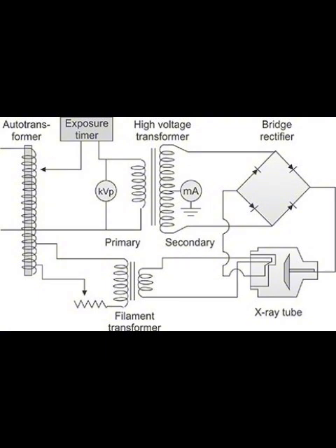And what are its main jobs? It has two critical functions. First, it takes the high voltage AC from the step-up transformer and converts it into DC for the X-ray tube, using the rectifiers we talked about. Precisely. Usually that full-wave rectifier bridge. Second, it contains the secondary coil of the step-up transformer itself, which is doing the boosting from volts to